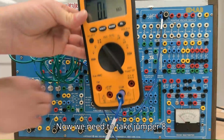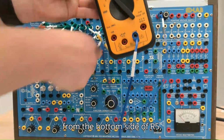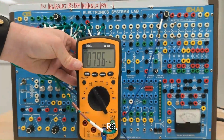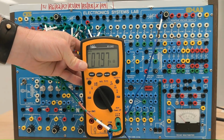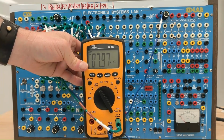Now we need to take jumper 8 from the bottom side of R5. The resistance measurement of R6, R7, R8, R9, 7.97 kiloohms.